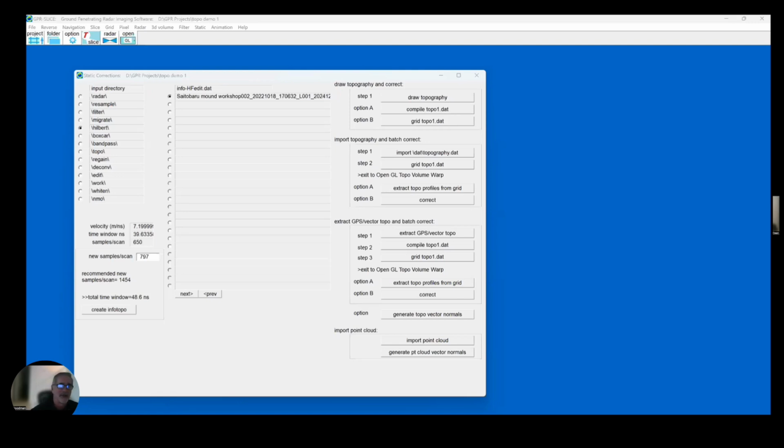you know, we work in relative normalization or absolute normalization. What absolute normalization is: when you put a gain curve on your data, you're stuck with whatever gaining you apply to your radargrams below that. So certainly, if you don't put in a good gain curve and you create a 3D volume on absolute, you may not get good imagery. So this is showing the data on absolute, where the ground wave was very strong, and then down below we didn't have a good gain curve.